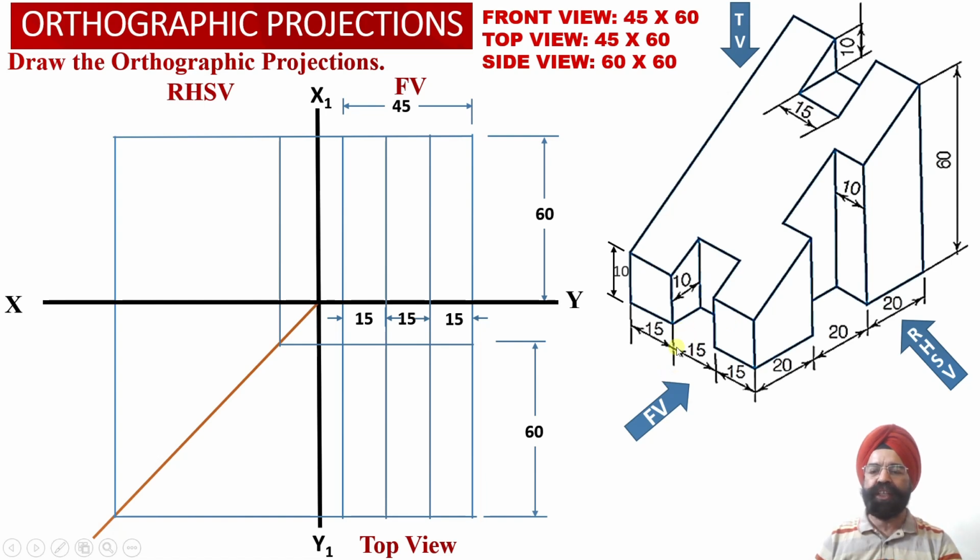Now we observe that this vertical slot at the base of the solid and this horizontal slot at the top surface of the solid, both of these slots are available centrally alongside the width of the solid. So now let us evaluate the center point alongside the width of the solid over here. So we have marked a distance of 22.5 millimeter from the right hand side face of the solid, and a vertical center projector line we have been able to obtain into the front view projections, and we have extended this vertical center projector line into the top view orthographic projections over here.